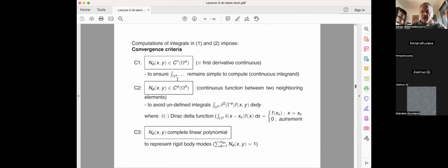In other words, when I go from one element to another along the same boundary, the two elements should be sharing the same interpolation. And in the 2D case, this is a bit that people do not understand. Initially, when I remember talking to people who are not used to finite elements, they thought the elements were just stapled together at the nodes, but they don't really have to be also glued together along the boundary, at least for this case. If you go for high order shell theories, they have to match also in first derivative and stuff like that. So it can be quite complicated.